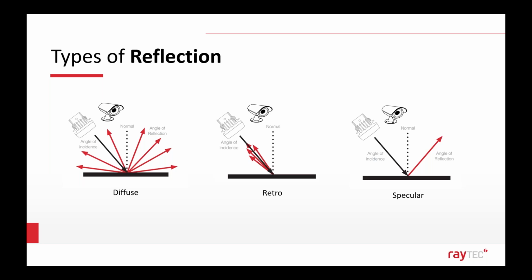This again is why camera setup is super important, and we've had just an example this week where we had a customer complaining that the lights weren't working, and it turned out that with some clever setup of the camera, I say clever, we adjusted the shutter speed primarily, turned off the integrated infrared. We were reducing the amount of bounce back from the plate, so it reduced the overall darkness of the image, but actually the plate was so much more readable because of it, and that's ultimately what they needed the system to achieve.